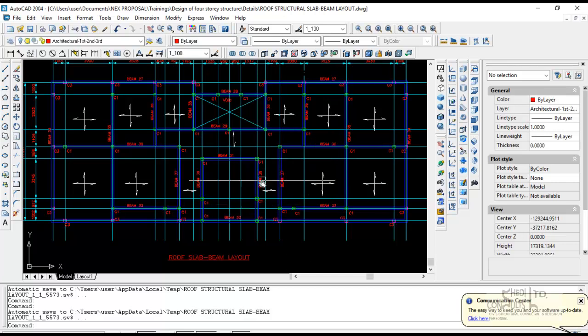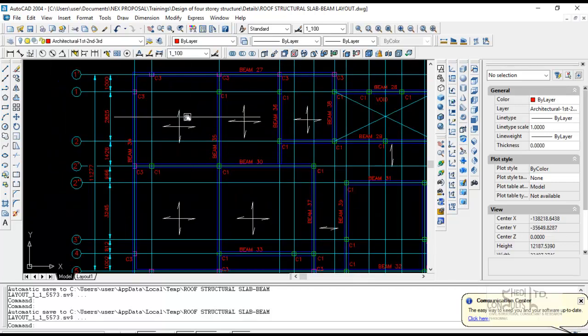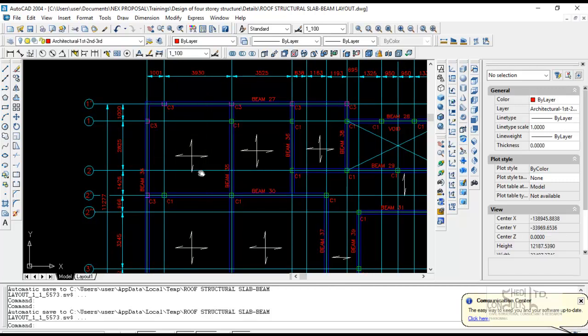And then some slab panels are one way. You can see this is a one way, that's a two-way slab panel. Remember the failure mechanism for yield lines. Yield lines form at the boundaries of edges, and then they terminate at the boundaries of edges. They commence at the intersection between boundaries, and so on. These are properties of yield lines.